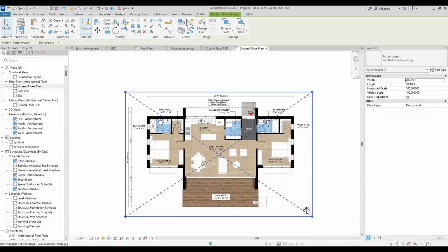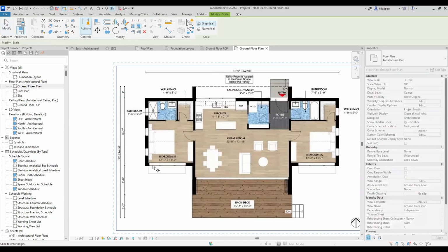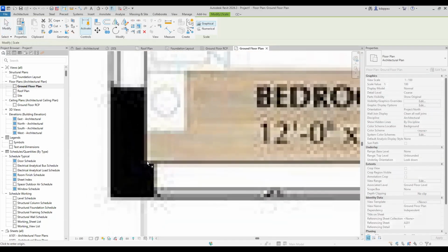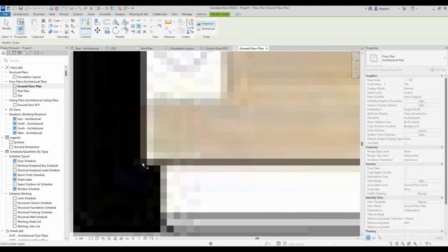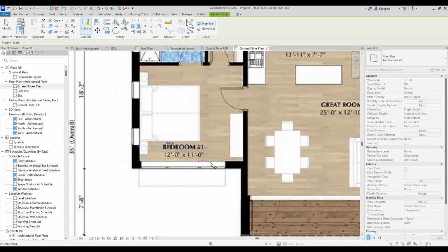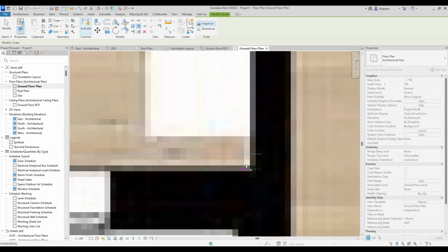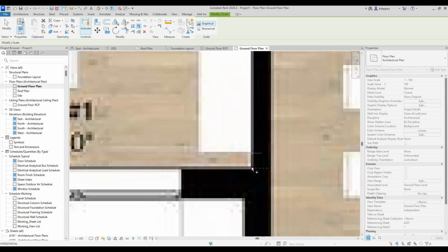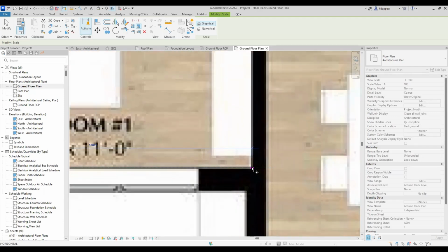So I'll take this one, select the image. Then there's a scale tool here. Under the modify panel here, you should see scale. Scale, keyboard shortcut is RE. So I'll click on scale. Then I'll click on one point. From the internal, I'll zoom in a bit from this corner here up to this internal corner here. When I click, it's giving me approximately about 5,140.